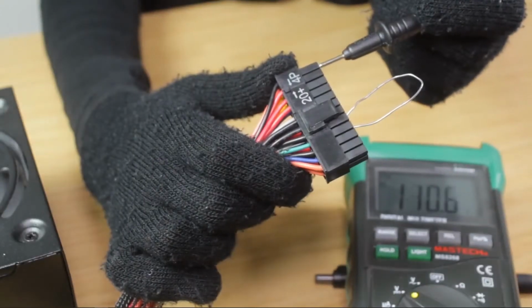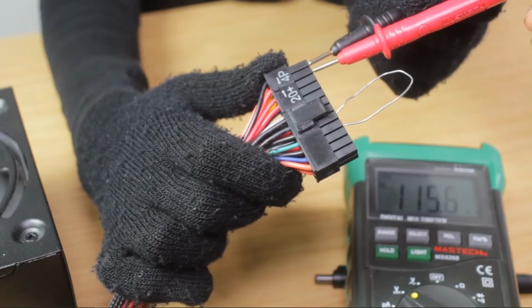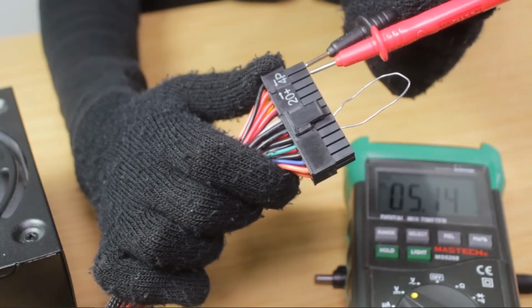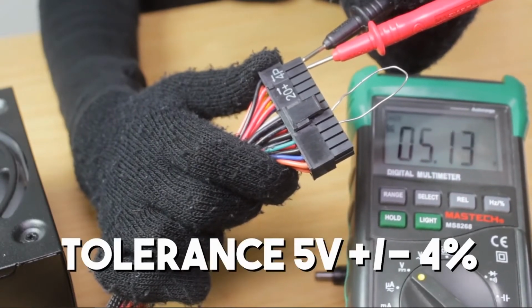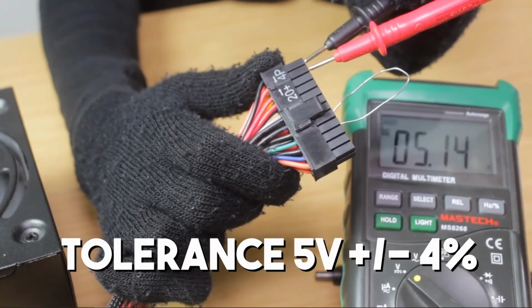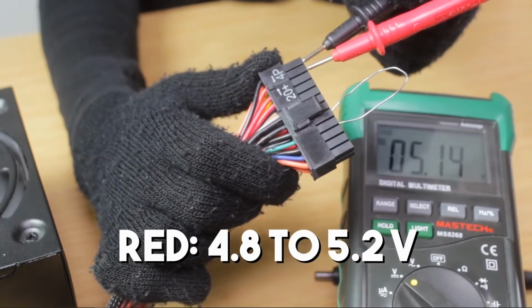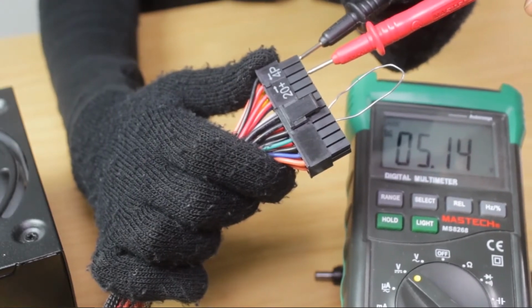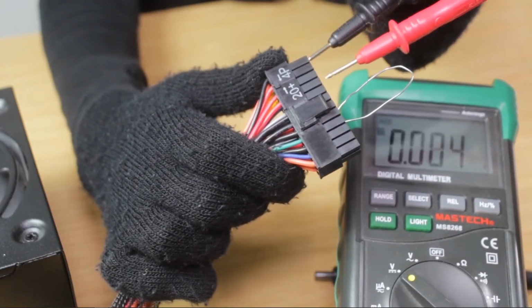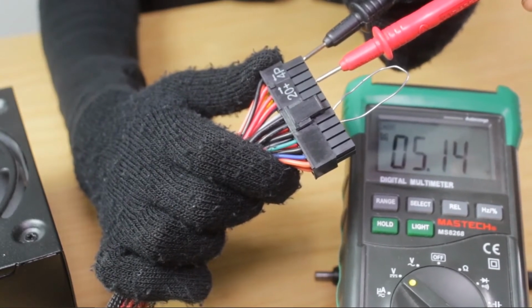Plugged on DC, and we're going to test. The next one is a red. I'm expecting 5 point something volt, 5.14. There's a tolerance of plus or minus 4%, and it's well within the range. So if you get anything between 4.8 to 5.2 is fine. Right, next one, the red again, 5.14, perfect. Next one, 5.14 again, perfect.